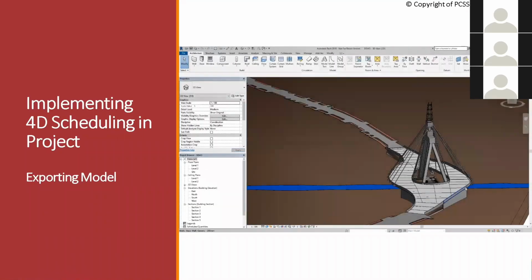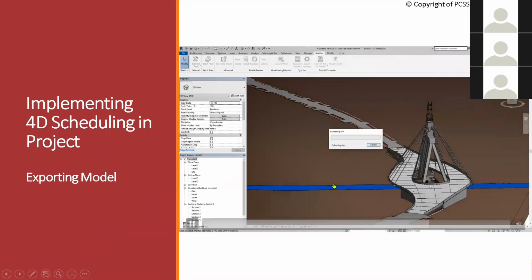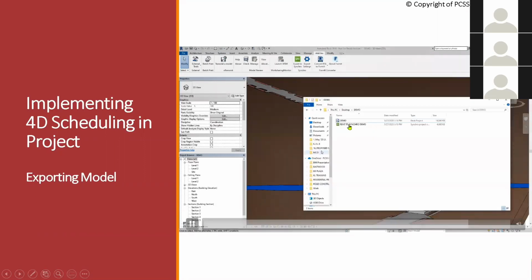This is the model that I want to export. With the Synchro Pro plugin, you export to Synchro. As you can see here, the file is an SPX file. Once saved, you can see that your model is here as an SPX file.